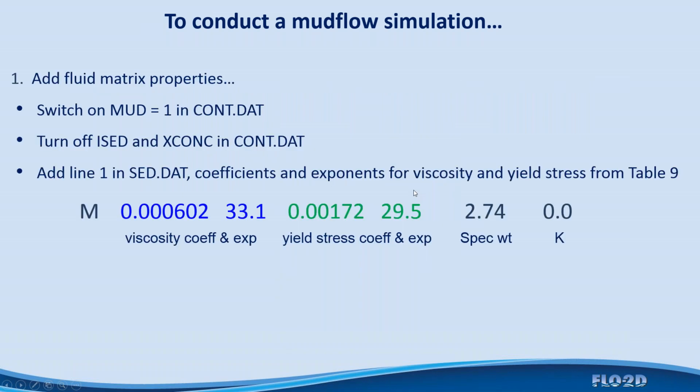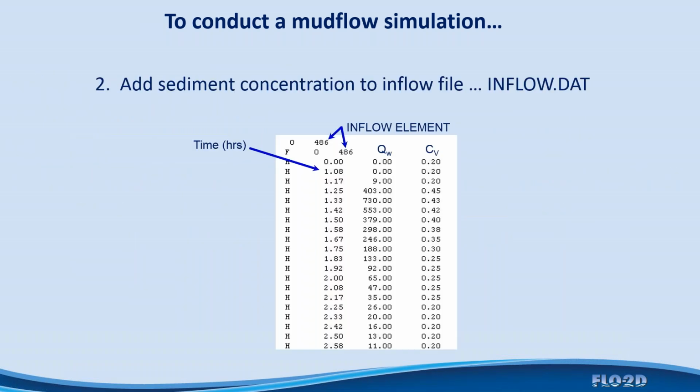That's this one right here, because it behaves like wet cement, and that's from my experience with it. So now, how do you distribute this concentration throughout the hydrograph? Well, you want to start somewhere around conventional water, because as you saw with the water going over that dam in the mud flood movie, that was probably around 20% concentration by volume.